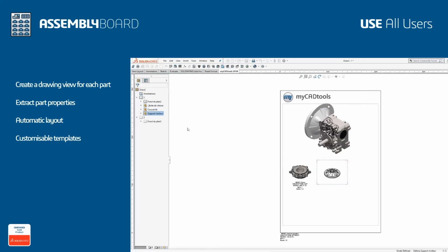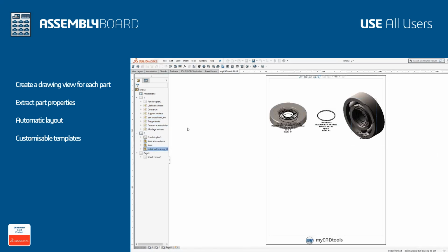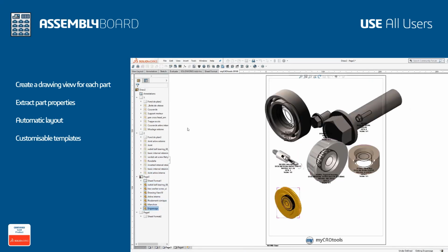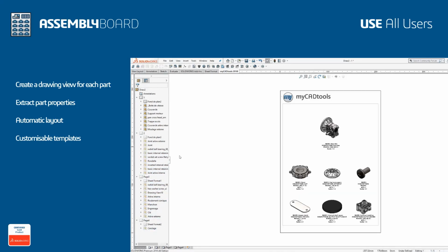A favourite layout can be saved for reuse, and it will save time the next time you use the tool. A pictorial representation of the BOM is generated automatically, showing the custom properties for each part specified. It's a useful tool to visually represent an assembly.